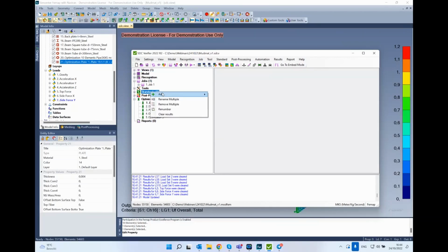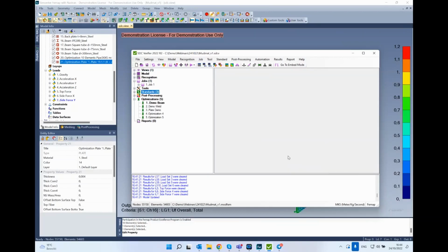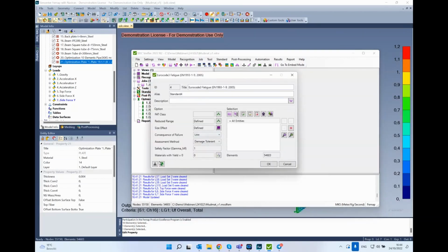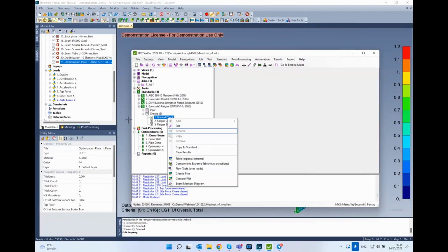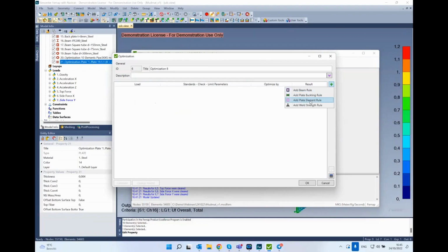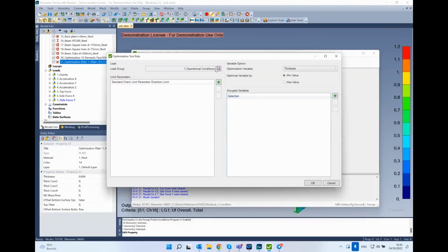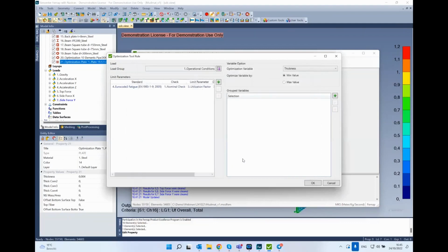It doesn't have any references to check the conflicts with other standards. So what I would suggest is to create, except the plate buckling, also a fatigue or a static stress check, and here we will have a nominal check. And then I would suggest to create a new optimization where I will check the plate elements according to the Eurocode nominal check of the utilization factors, and then run this check with the new model and see if that's actually okay.